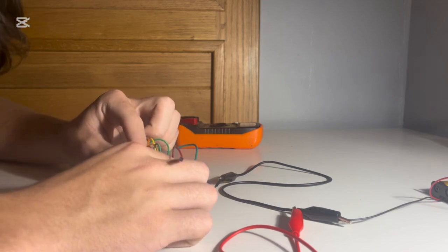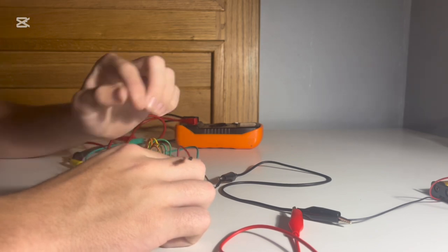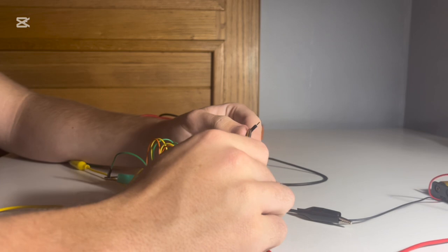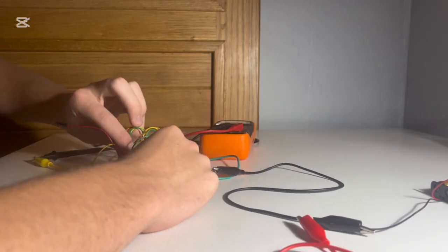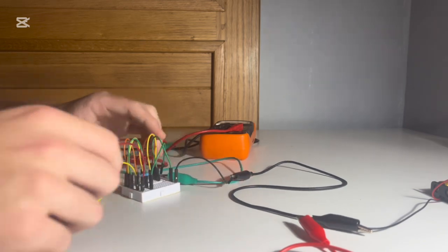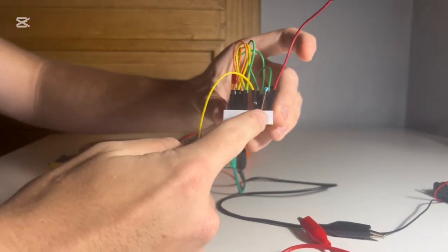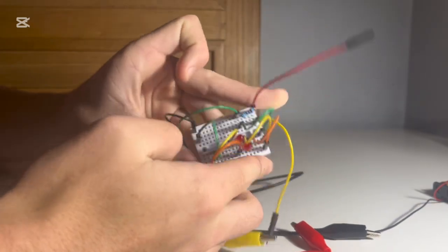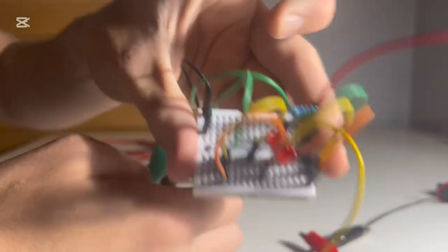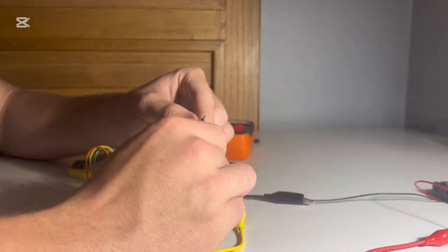Now we will measure the voltage across the resistor in the main circuit, positioning the voltmeter so that it is once more in parallel with the component it is measuring. You can see that the voltmeter has been placed in parallel with the resistor connecting the power supply. Once more, we get a reading of 4.1 volts, which is the volt drop across the resistor.